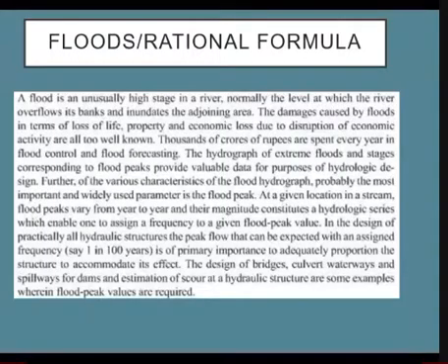The hydrograph of an extreme flood and the stage corresponding to the flood peak provide valuable data for the purpose of hydrologic design. Further, of the various characteristics of the flood hydrograph, probably the most important and widely used parameter is the flood peak. At a given location in a stream, flood peaks vary from year to year, and their magnitude constitutes a hydrologic series which enables one to assign a frequency to a given flood peak value.